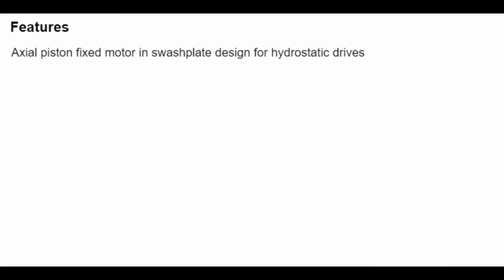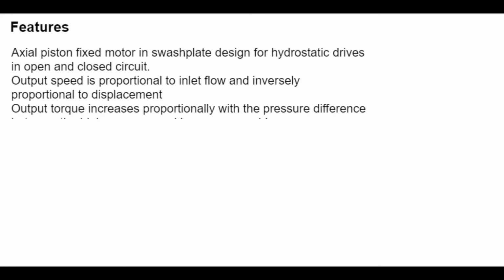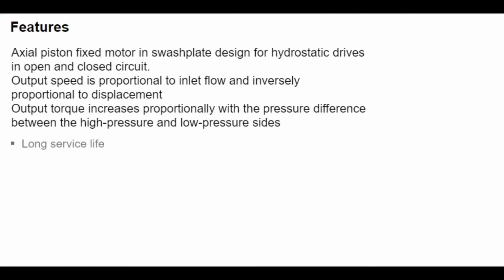The Rexroth axial piston fixed motor A4FM in swash plate design is specially designed for open circuit and closed circuit hydrostatic drives with minimal space. The fixed swivel angle makes the output speed proportional to the inlet flow and inversely proportional to displacement. Output speed can only be increased by increasing displacement. Output torque increases proportionally with the pressure difference between the high pressure and low pressure sides. The hydrostatically mounted slipper pads also ensure long expected service life and optimal efficiency.